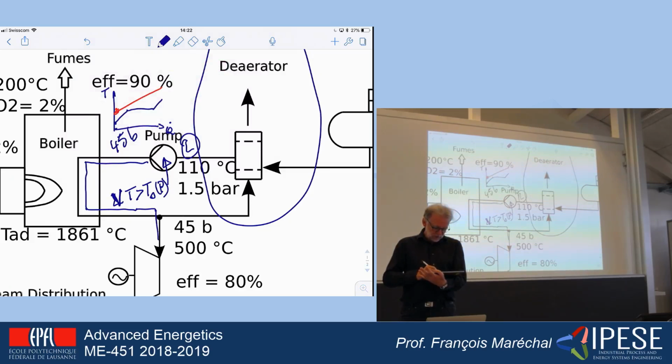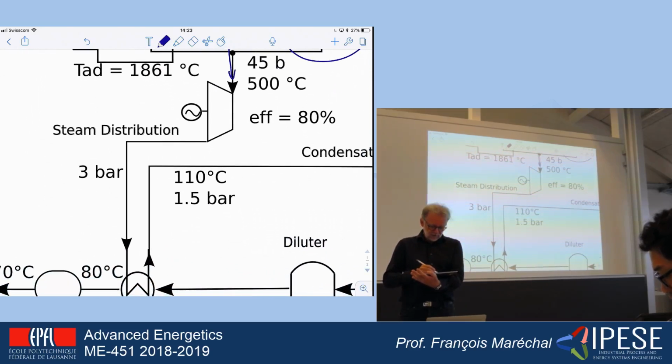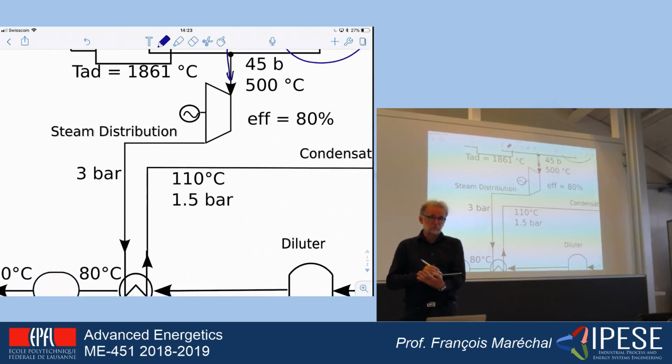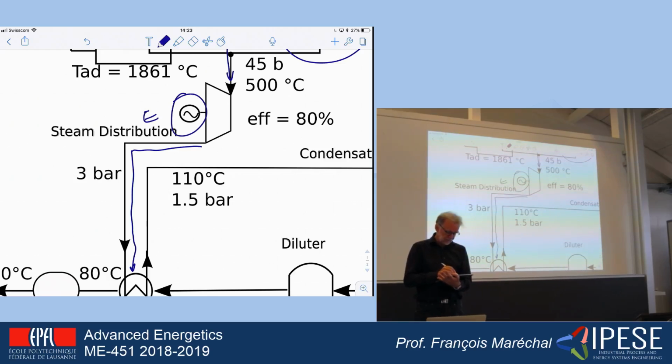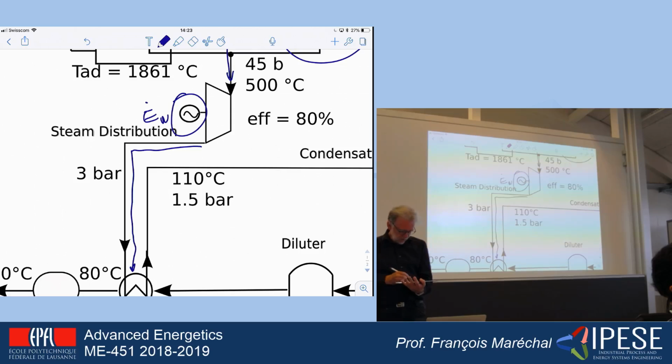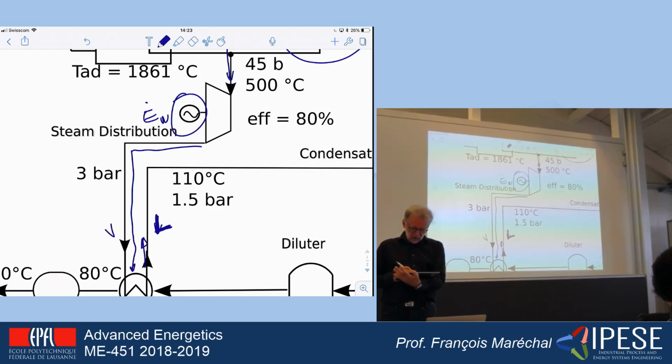And afterwards, the vapor is going to be used mainly here in a turbine, where it is going to produce mechanical power, which means that it is going down in pressure. So the pressure is now here, following still this flow. It is going to come here at a lower pressure and has delivered a certain amount of mechanical power. Once it is there, it is going to go from the gas state to the liquid state. So here we are at the vapor state, and here we will be at the liquid state, coming back here. And what you can see is that the pressure is lower.